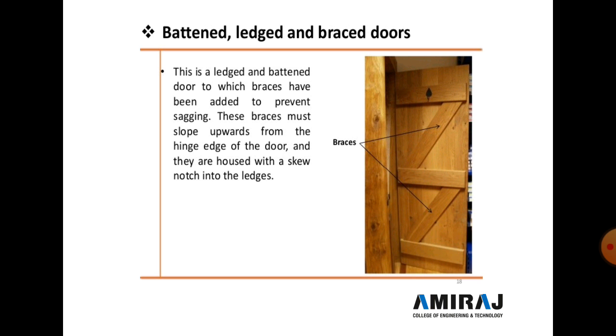So this type of the ledge or batten door, to which braces have been added to prevent the sagging. So these braces must slope upward from the hinge edge of the door, and they are housed with the screw notch into the ledges.